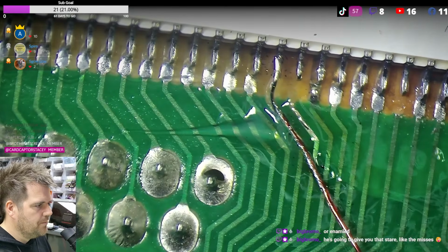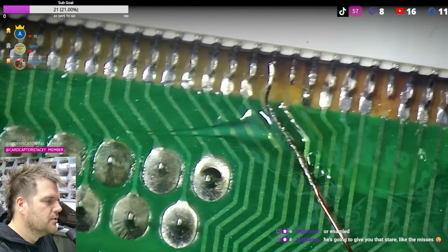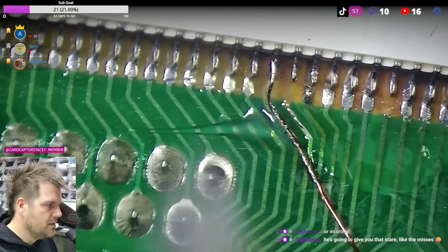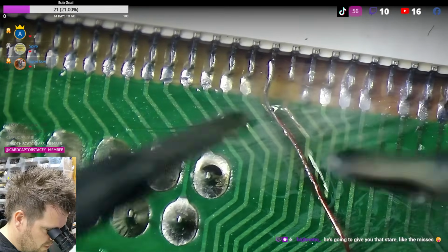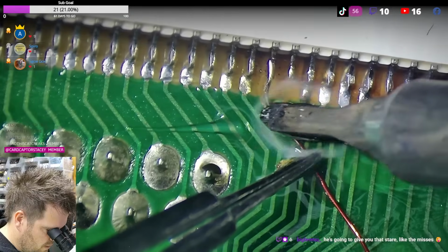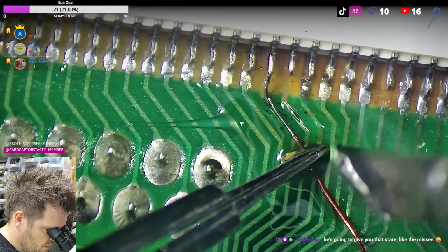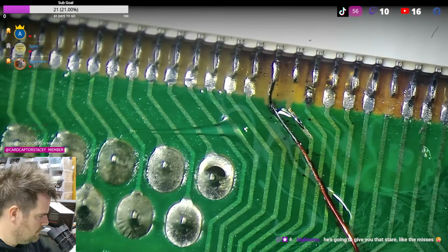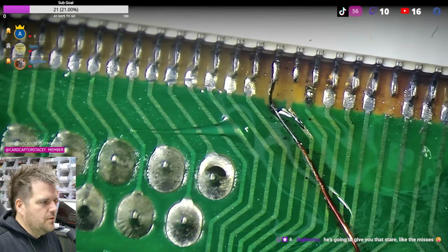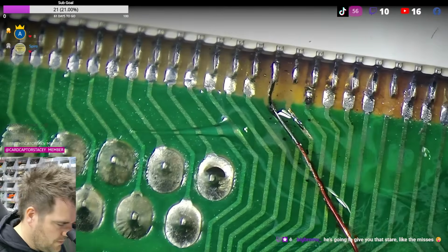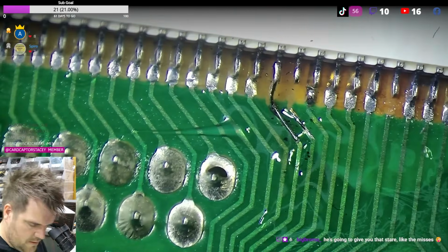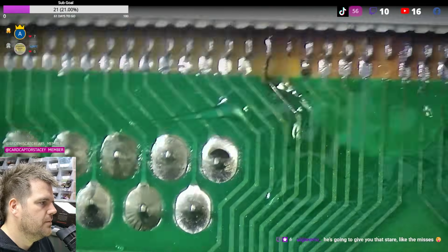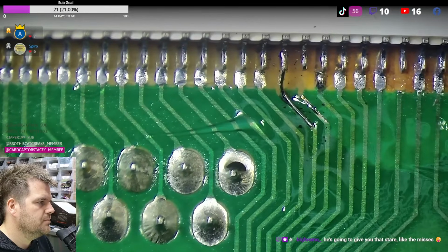It's still got a little bit of the red enamel on. But what I'll do is hold it in position and strip it while it's there. So this will try and fly off with all the heat, but there we go, much nicer. So just push down, apply the hot air, and then just leave it for a few seconds and it'll all completely bond and look nice. And then you can nice and easily cut this one. And that's what you end up with. I'd say that's a nice looking one, nice and clean.